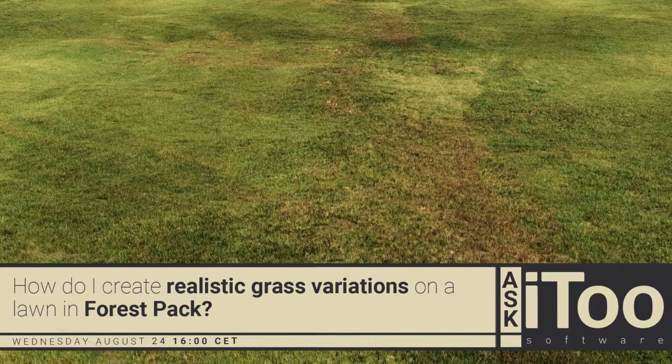Sometimes the only way to do it is to forget expanding to the clipping spline automatically, create the array a bit bigger than the spline manually, either using an X and a Y spline or just using XY dimensions, and then use a separate spline just to clip it afterwards. That way you can just move it into position using the transforms or whatever. You can just put it where you want it and then cut it afterwards, rather than let it create the spline perfectly for you. And that gives you the most control, but it's less friendly to set up, I guess, and less easy to just click on loads of stuff and fill up areas. But if you've got a really tricky roof, that's probably the only way you're going to be able to do it.